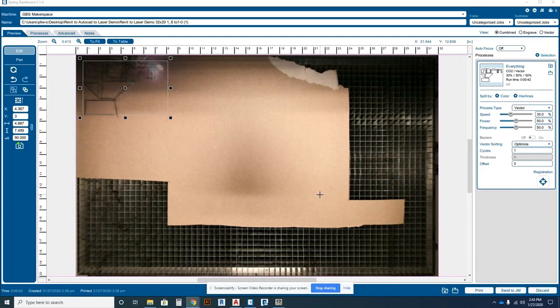Here you're going to see the laser cutter in action. It's following the path of the lines, and the camera's catching the progress. Make sure you supervise the machine as it goes, so that way if anything catches on fire, you can hit the big red stop button on it and kill the power. Make sure you open any windows, pull any smoke alarms that you have to, just in case you have a problem. Everything should come out just fine.